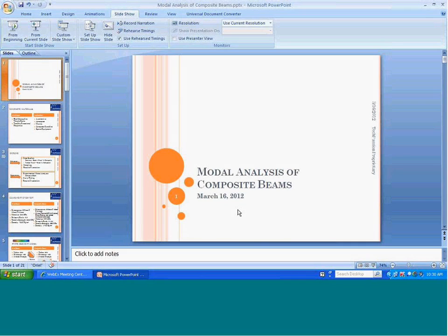And for dynamic loads, given that the resonance frequencies appear at much higher values compared to beams made of steel, what that means is you could be putting rotating machinery or any kind of exciting loads which could be operating at higher RPM or higher speed, and which has its own advantages.